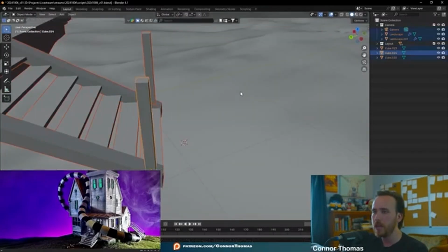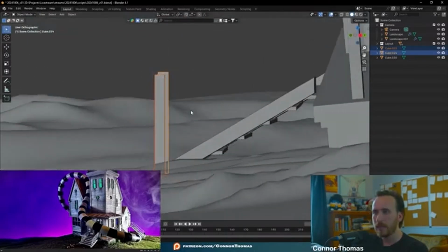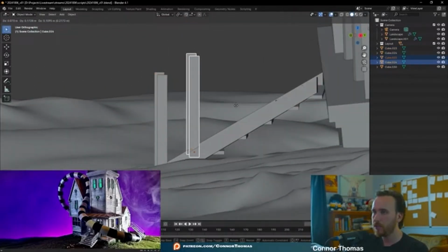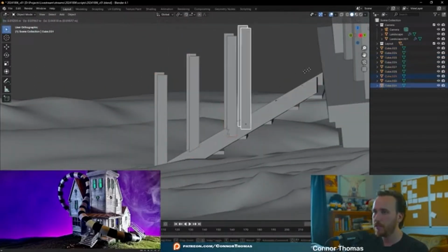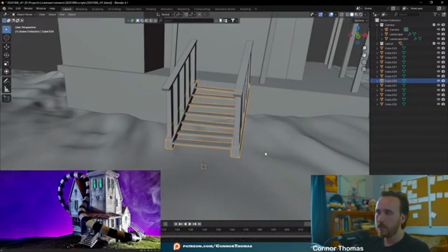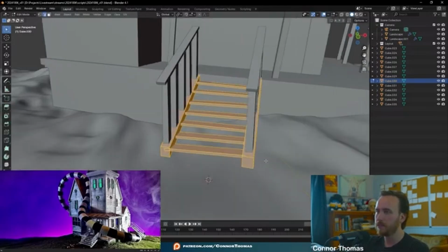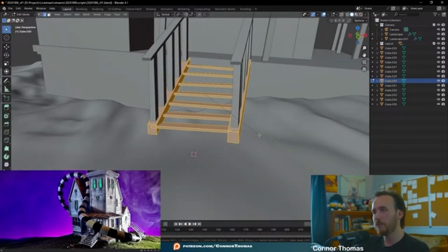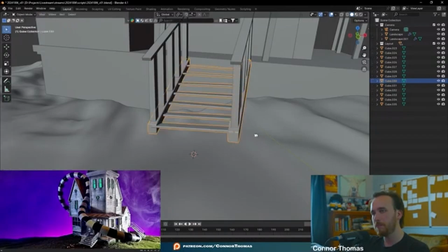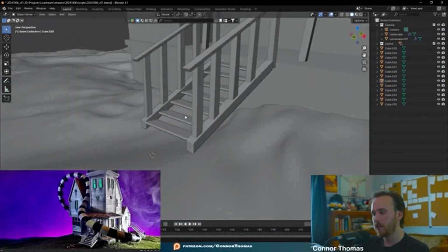But if you're doing synthesize, you're probably setting your measurements there, correct? Gonna line that up, and then we're just going to duplicate this upwards and create ourselves some railways. And you know what? I'm actually going to not apply all transforms. I'm going to apply specifically just the scale, because we don't want to apply the rotation. But now we can go ahead and add in some nice bevels to this wood here. And that's already going to make it look a lot better.